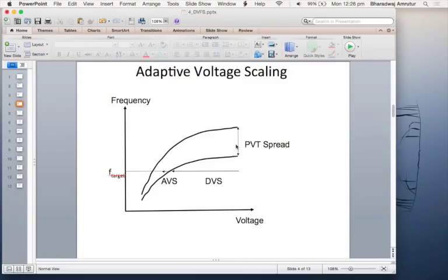So this is what is called adaptive voltage scaling, but today we will focus first on dynamic voltage scaling, and next class we will come back and look at adaptive voltage scaling. Because this problem of knowing where your chip actually is, that is a tricky problem. How do you figure out what your chip is? How do we get a curve? This curve is obtained by basically timing analysis. The most accurate way, if you had good models, so the transistor models are good, which is usually the case now for digital design, is that you can use circuit simulation to get this curve.